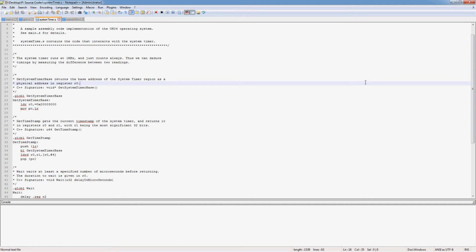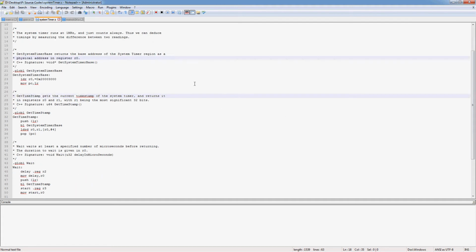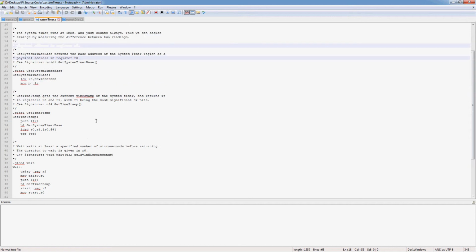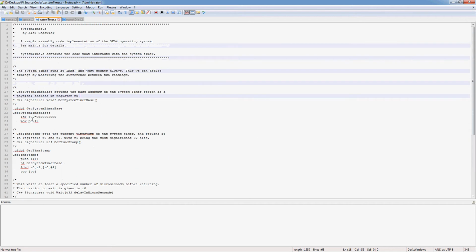This video is a walkthrough of the Raspberry Pi lesson OK04. What I have here is the code for the system timer. This code allows you to set a delay, basically. It starts like the other ones with a global function, get system timer base.